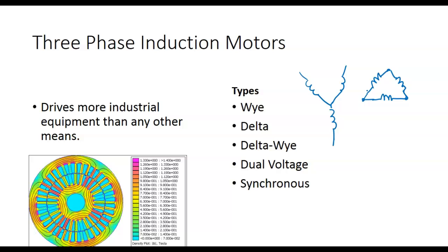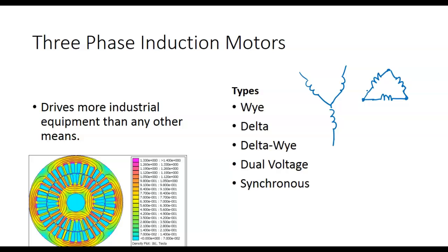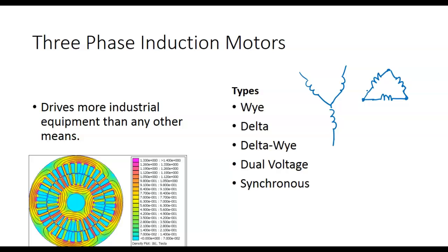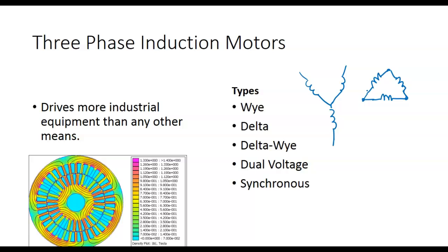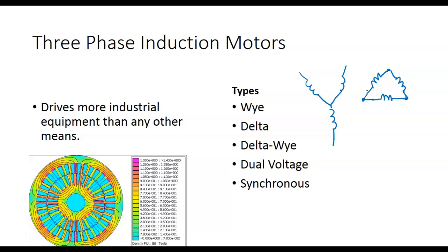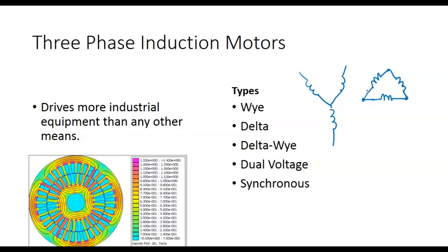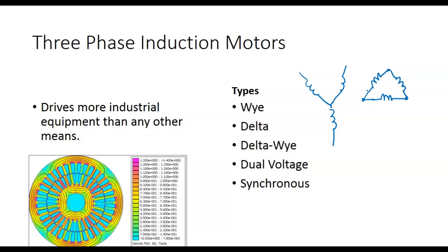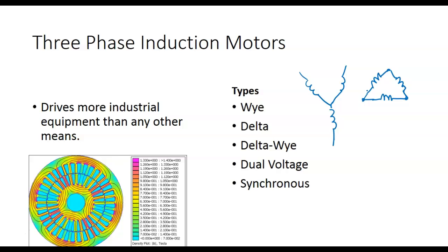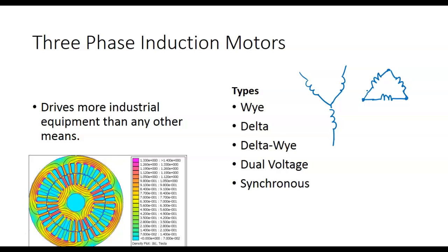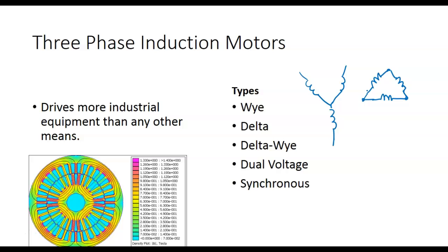We don't pay a current bill, and we don't pay a voltage bill. We pay a power bill. So a motor's rated at a voltage, but it might be a 5 horsepower motor. So that means if you wire it 120, it's going to run 5 horsepower. If you run it 240, it's going to do 5 horsepower. It's about 746 watts per horsepower, but when we wire it high voltage or low voltage, it's going to cost us exactly the same amount of money to run it because we're paying for horsepower.